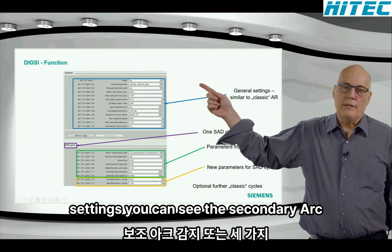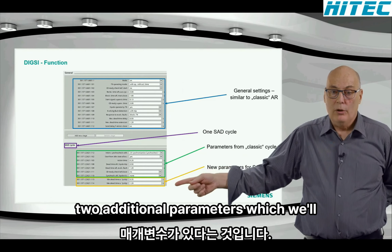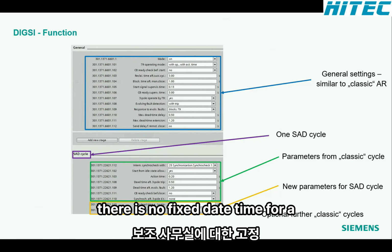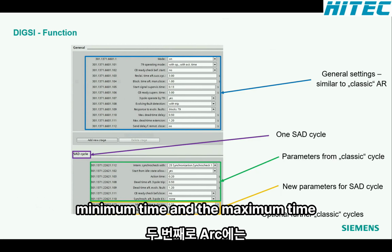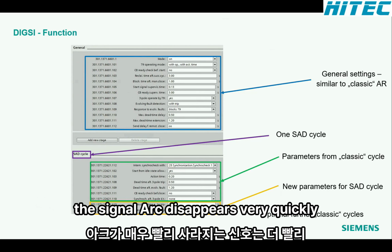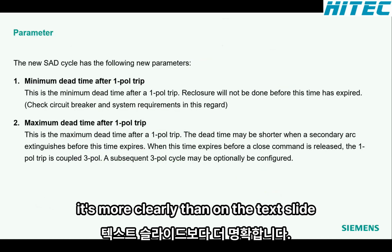So in the settings, you can see the secondary arc detection auto reclose settings are exactly the same as the normal auto reclosure. The only difference is the cycle, the secondary arc cycle has got two additional parameters, which we'll look at in detail later on. It's your minimum dead time and obviously a maximum dead time. There is no fixed dead time for a secondary arc. The secondary arc only has a minimum time and a maximum time. If after the minimum time, the secondary arc has disappeared, it'll reclose immediately. The secondary arc disappears very quickly, can go even quicker, but we will have some graphic examples. I'll show you those two timers in graphs just now. It's more clear than on the text slide.